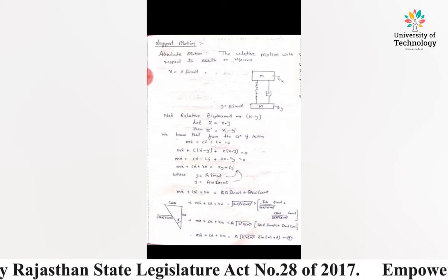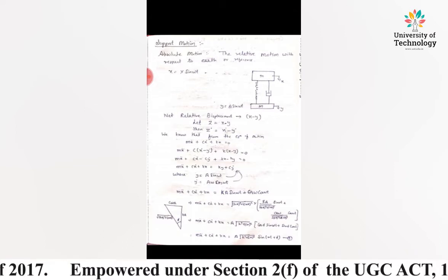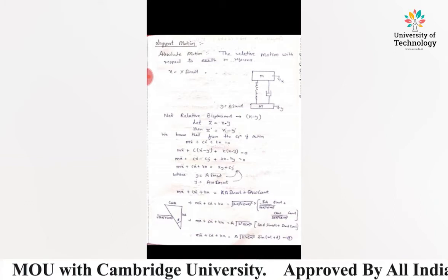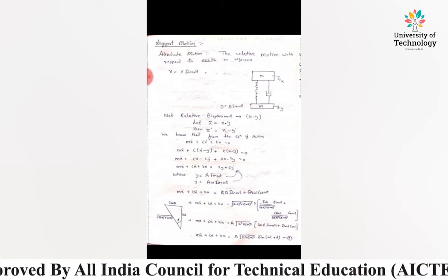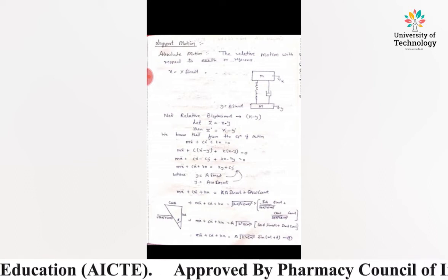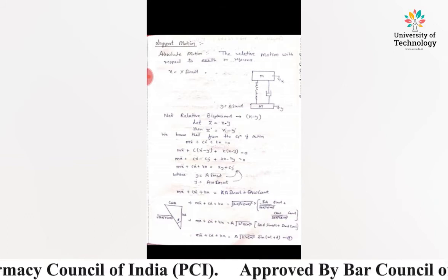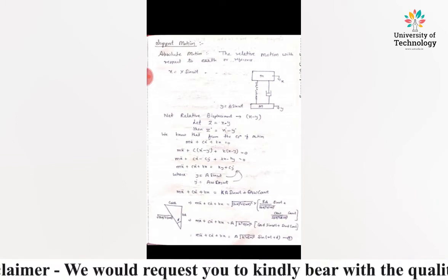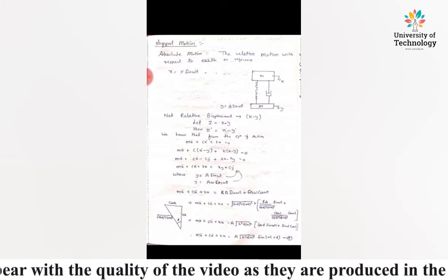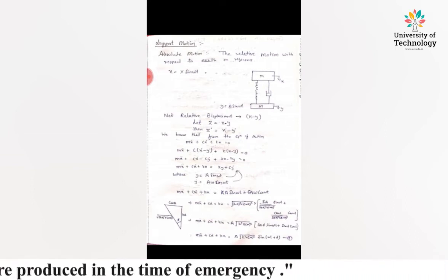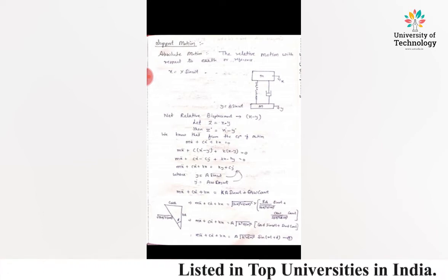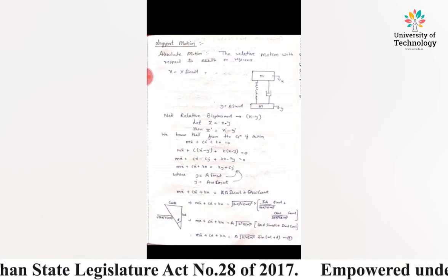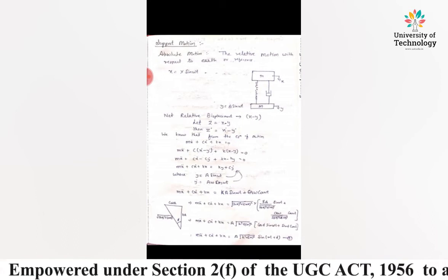If we take the root value outside the terms of sine and cos, that is the root of (kA) square plus (c omega A) square, then the equation can be written as m x double dot plus c x dot plus kx is equal to the root of (kA) whole square plus (c omega A) whole square, into, by dividing by this root value, kA upon the root of (kA) whole square plus (c omega A) whole square times sine omega t plus cA omega upon the root of (kA) square plus (c omega A) whole square times cos omega t.